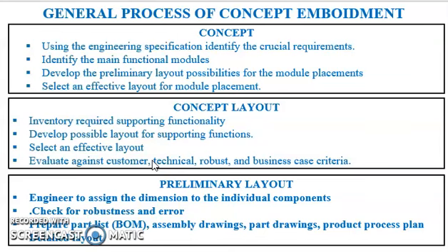supporting or auxiliary functions. Auxiliary functions come into the picture due to implementation of the original function. For example, a battery pack is selected to supply power to a subsystem. Now, auxiliary functions have to be implemented to hold the battery pack in the system and to route the power supply to different sub-assemblies of the product. Incorporation of main, supporting and auxiliary functions produces the rough layout of the product.